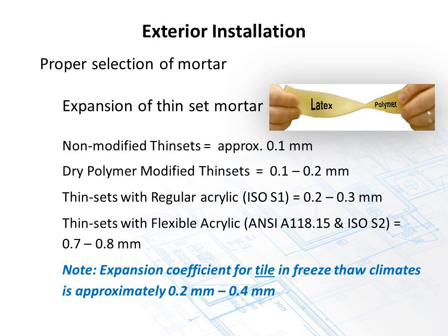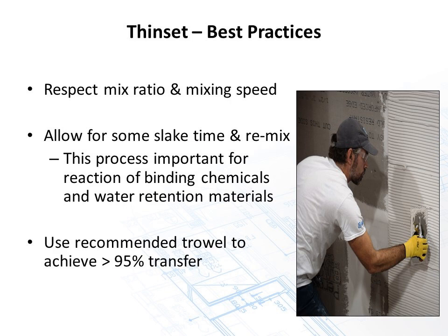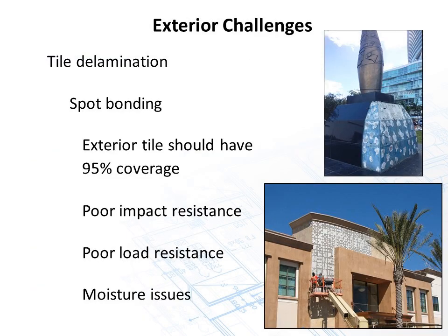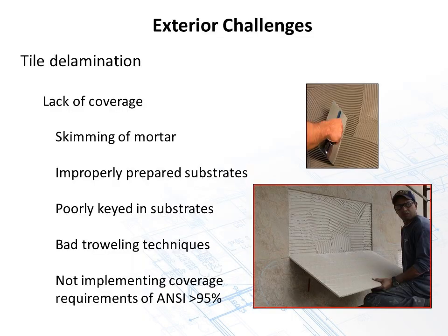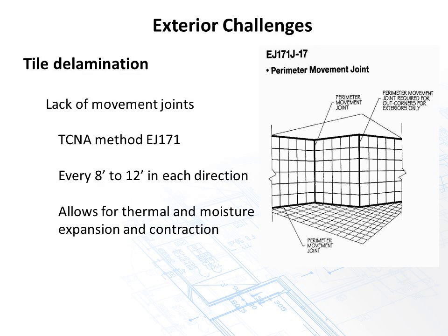He also asked a question about how you would handle exterior outside corners, and I think you mentioned it in one of the slides about using expansion joints, right? Correct. Is that how you handle all exterior outside corners with expansion joints? They should be, yes. Exterior should have expansion joints, as detailed in the TCNA handbook. That's directly out of the handbook. And again, I'll stress, exteriors only. And Chip said he'll call you later.